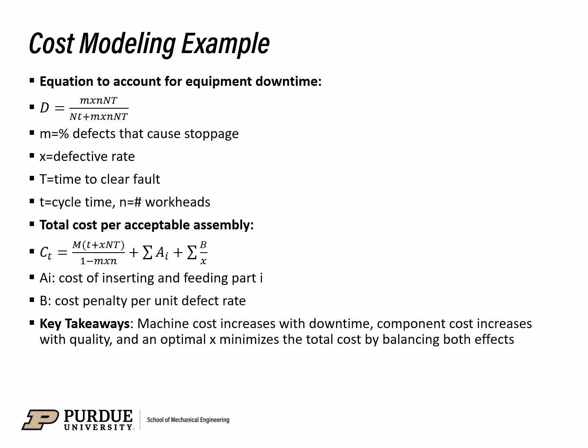This model is nonlinear. It tells us that as the number of stations increases, or as the defect rate increases, the downtime is going to grow disproportionately to those values. This becomes very critical in high-speed operations. Let's look at an example. If your cycle time is 2 seconds and you run 30,000 parts a day, then a single 10-minute fault is going to cost 300 units. When you multiply this by number of lines, staff, power, and scrap cost, you can very easily see how that downtime is going to translate directly into dollars.